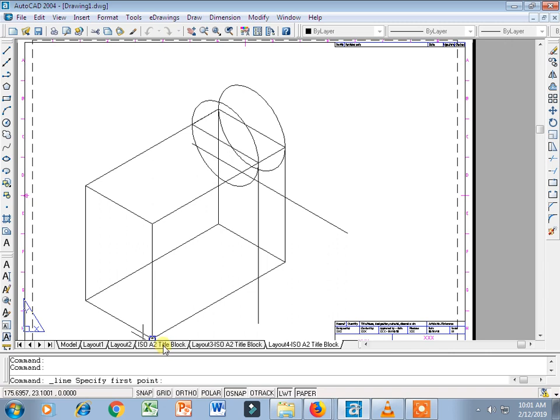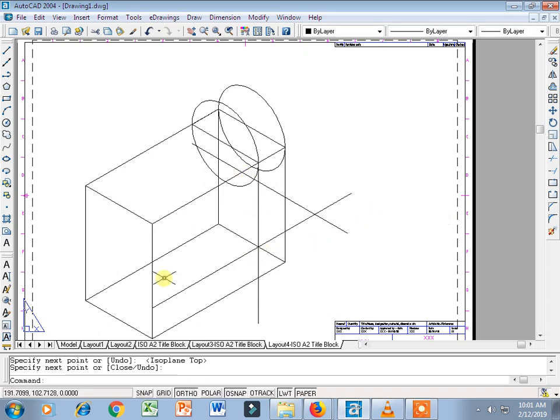Now we will draw one line from this corner, and height we will give ortho on. Height we will give 40 mm. Enter. Now from 40 mm we will press F5 and will complete this orientation. Now we have got this portion done. Now similarly from this corner also we will join this. So we will start from this, we'll give this orientation F5.